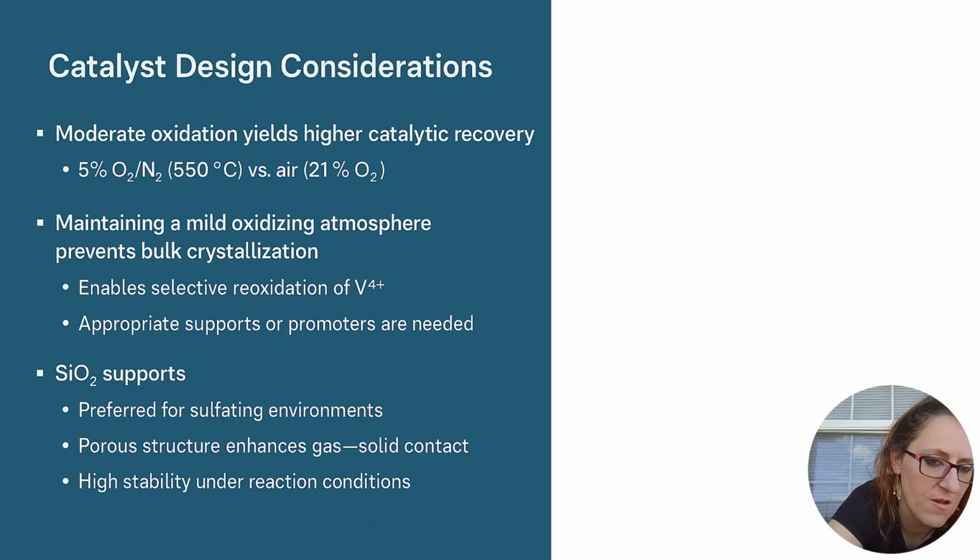In oleum production, where sulfur dioxide is converted to sulfur trioxide, the reaction occurs under high temperatures and highly acidic gas conditions. Catalyst performance depends on maintaining a stable molten vanadate layer. A well-designed catalyst must distribute vanadium uniformly, prevent iron-silica interactions, and dissipate heat efficiently. Consequently, pore architecture, heat transfer, and bed packing are vital design parameters that help prevent local hotspots and gas maldistribution.